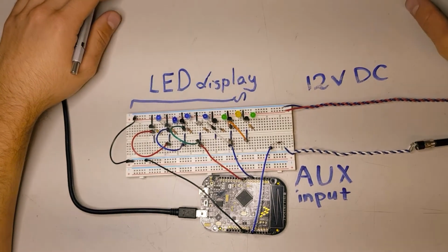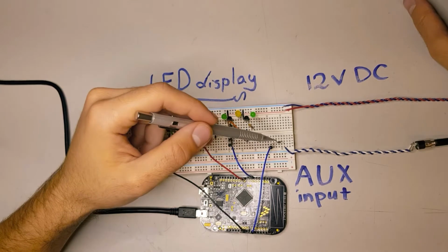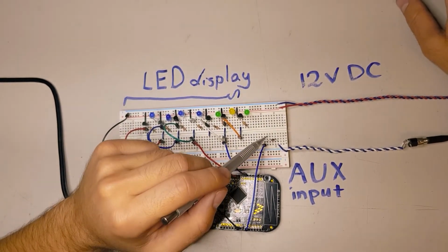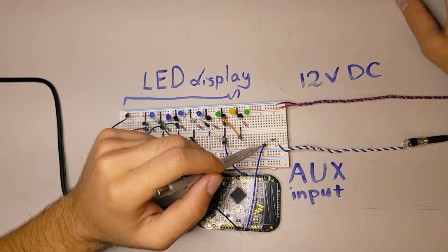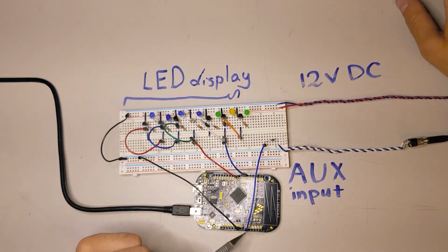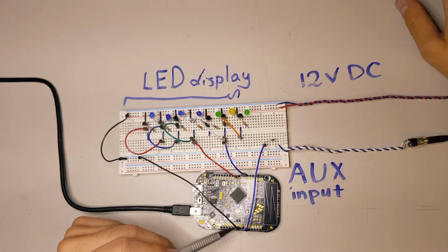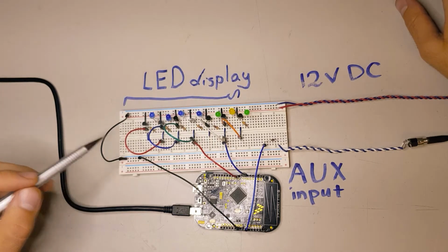For the circuit of this project, we inputted an analog signal through a speaker across a diode, which functioned as a noise cancelling element. Then it was jumped to an analog input, which is PTB0. The ground pin of the mbed was jumped to the negative bus of the breadboard to have a common ground for all the circuit.